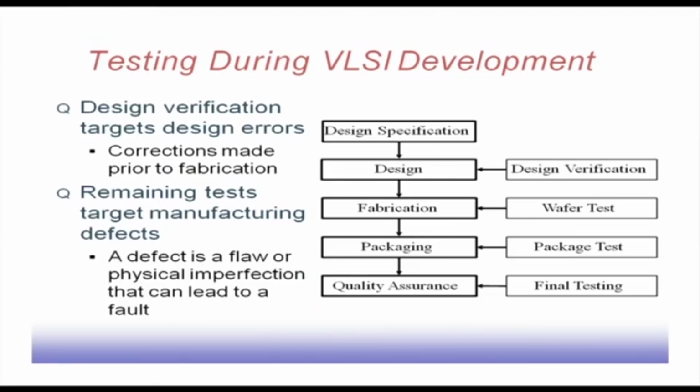But the basic problem with the wafer level test is that at that point these wafers are open. They do not have any protection, like packaging and all that. So, they cannot tolerate voltage fluctuations or very high voltage, very high power, etc. As a result, this wafer level test is very delicate, and we need to take special care while doing it.